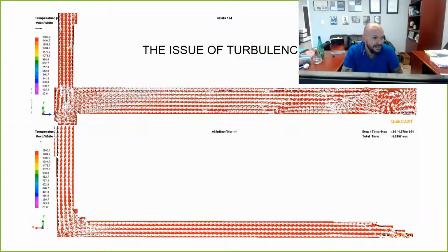It's disgusting. Now, both of these are still running live. And the one on the bottom is in perfect equilibrium because we've just got a beautifully, perfectly controlled filling system, right? No surface turbulence whatsoever, which means no bellows action, no decomposition of the mold, nothing can get in. We've got perfect control of the metal. Very simple manipulation of the metal using simple geometric manipulations.